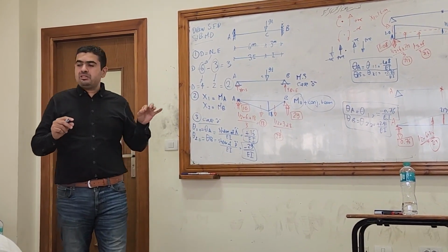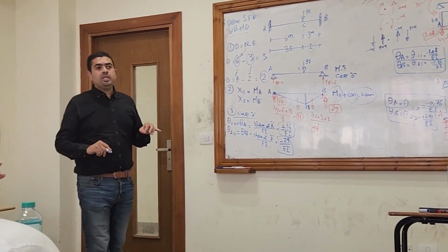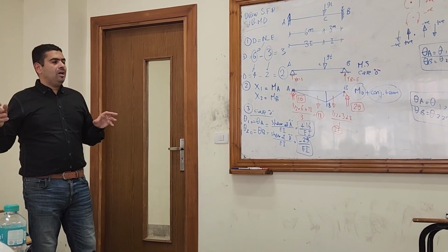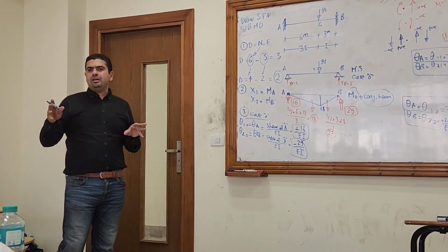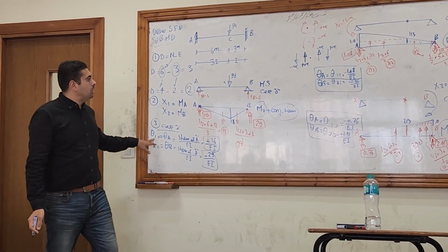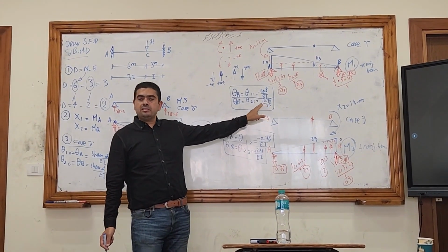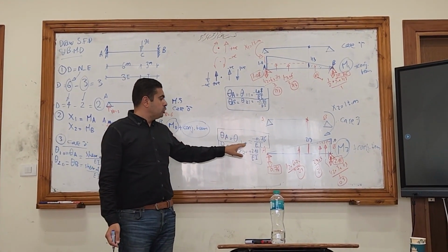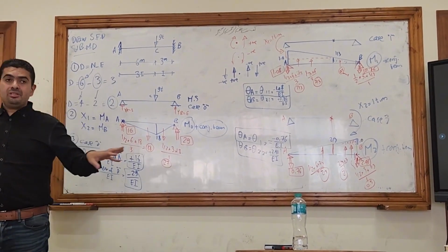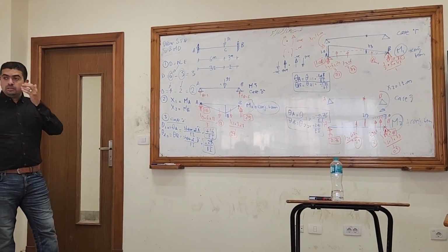The displacement that is called 1, 2 and the displacement that is called 2, 1, they have to be equal. I don't mean the sign, I mean the value, okay? So here, 2, 1 is 0.76. 1, 2 is also 0.76. So this is a very good check to make sure that I am on the right way.